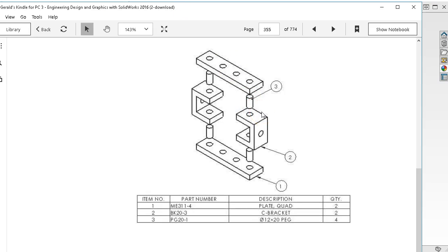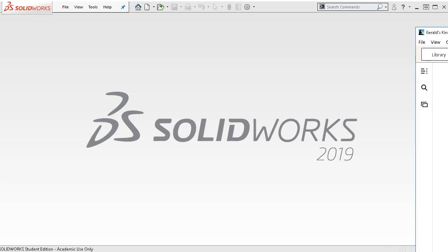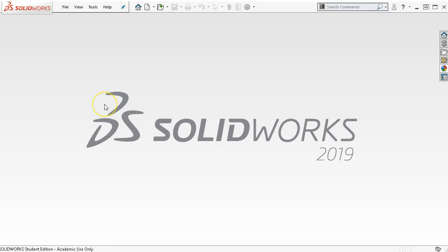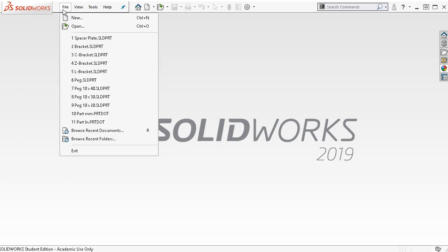Alright, so to start the assembly, we're going to bring in the items, and the recommendation is always that you bring in one item at a time, put it into position, and then bring in the next item. If you bring in all of these parts, good luck with that. Not my favorite thing to do, and I have had plenty of assemblies that I've corrected or modified where we did a lot of hiding, we did a lot of suppressing, just so it wouldn't freak out as bad.